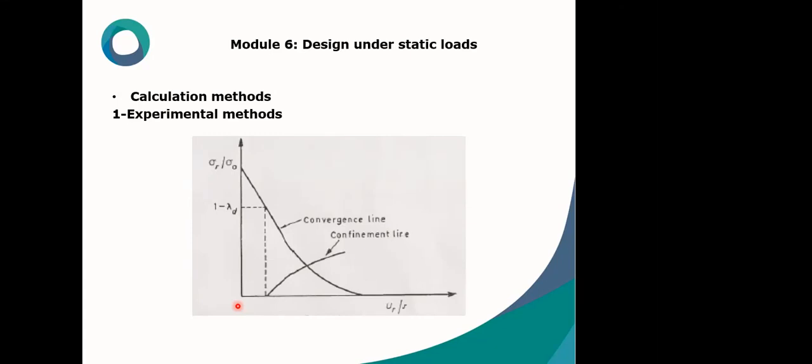Another point to explain will be the simple method to conduct two-dimensional modeling. Tunneling construction, in fact, is a 3D problem and will require some tricks for simplification. Numerical modeling usually analyzes the plane strain condition. And in order to simulate the excavation stages that are in fact a 3D physical issue, the numerical model uses